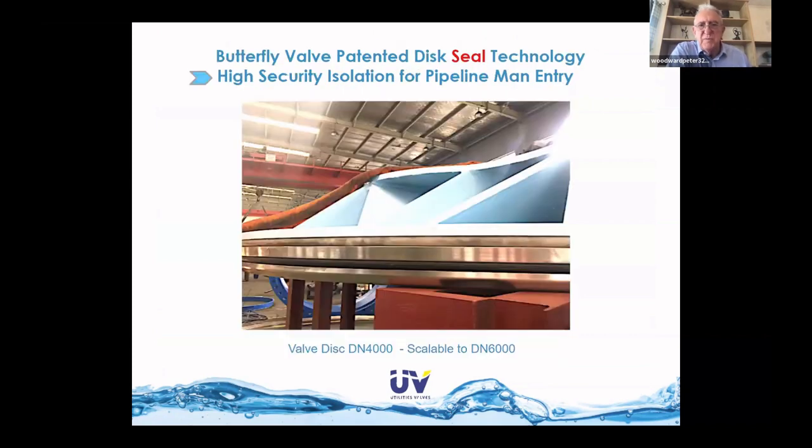And if we just pause for a moment, this is highly relevant. We developed and patented a seal technology for these very large butterfly valves. And if you look at the edge of the disc here, you'll see 2 different types of seal. This allows man entry into the pipeline against the full static head of water, the other side of the valve. So high security isolation, very much part of our theme, and of course extremely important for Hyperloop.